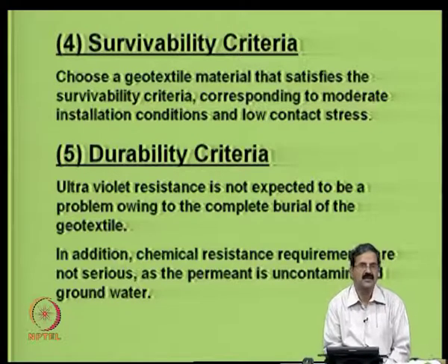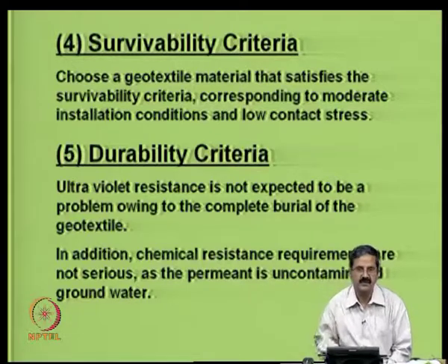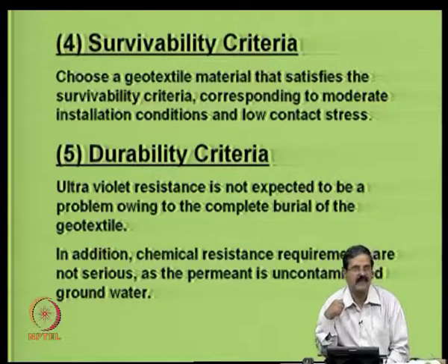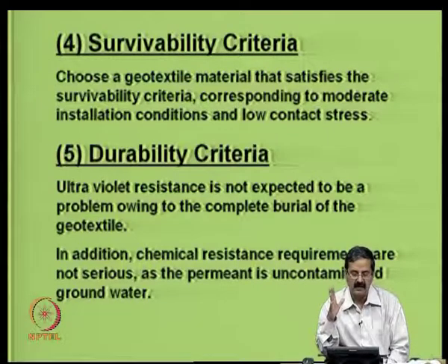Okay. Now, that condition is totally different, and you are trying to put stone pitching also, and the dropping of stones is there; they are somewhat different. So, the filter criteria, the chart you should use, will be different here if the flow is dynamic. Okay. So, these are all very important, and durability is also.